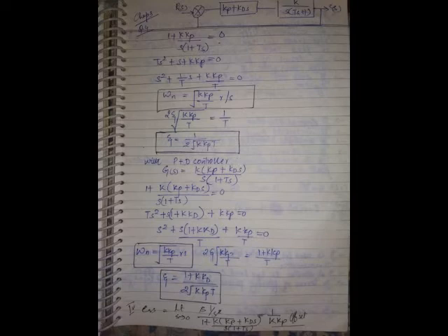For sinusoidal input, because the phase of the controller output is exhibiting phase lead characteristic, this controller is similar to a phase lead compensator. This is the implementation of a phase lead compensator, which we are now calling a P plus D controller.